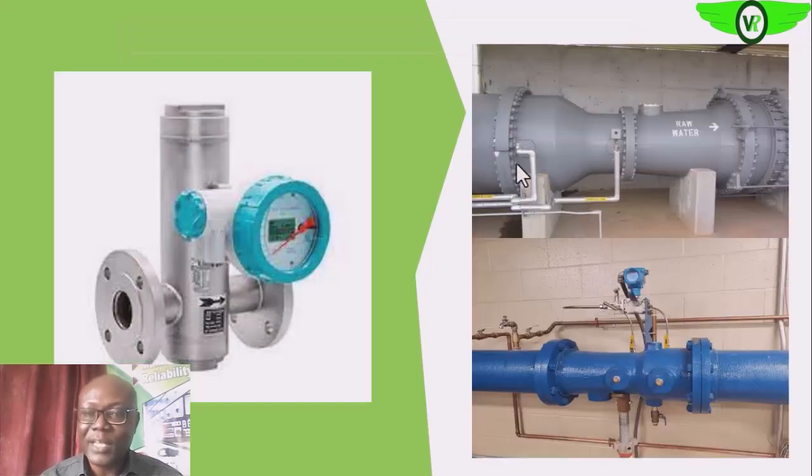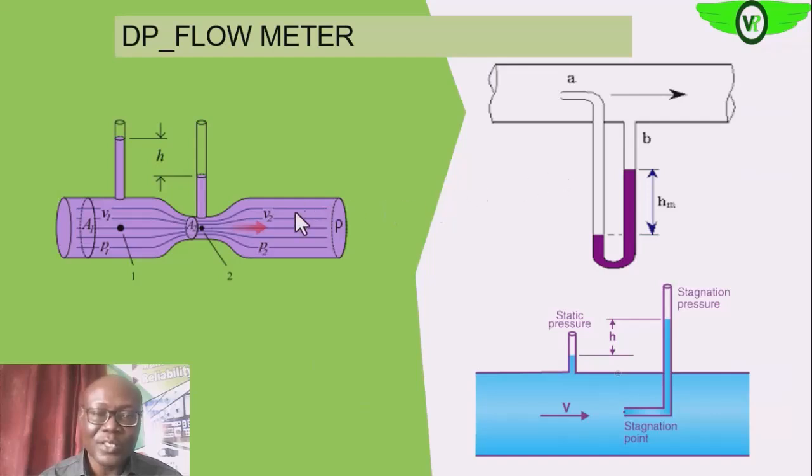So this is an example of a venturi tube. Okay, so you see the tapered end. This is the tapered end. So it's just like this end now. Remember, our goal is to create a restriction on the flow. Okay, as you do that, then the flow velocity will momentarily reduce. That will make pressure want to go up, which is indicated on this leg of the impulse line.